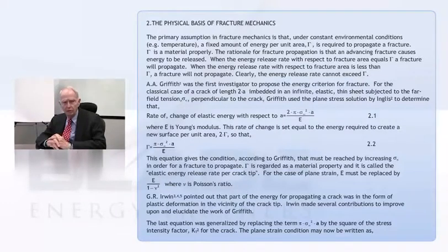But then, of course, you know that when you look at something like steel, you're looking at yield points of the order of 100 KSI, or 100,000 PSI, compared to Young's modulus of 30 million. So you can see that there's a big drop, and the flaws in crystalline material like steel come from different sources. I guess that was why Griffith really wanted to start with something like an amorphous material so you could have a better judgment of what's going on, and also you can degrade the material by exposing the surface to different environments.